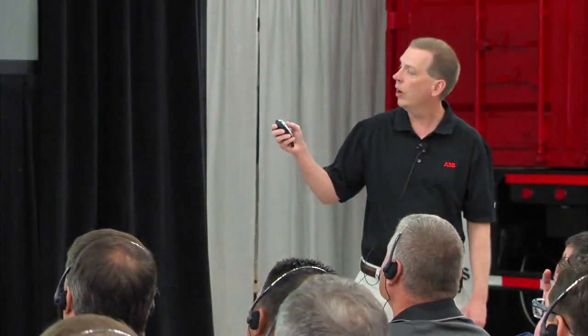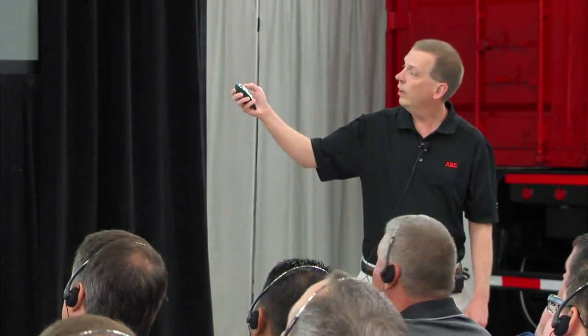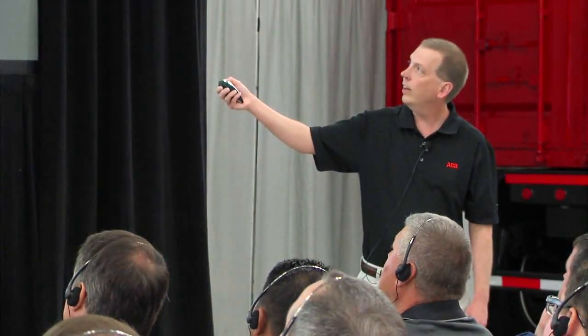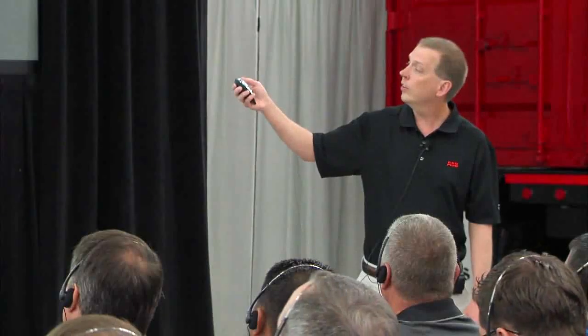What I was trying to say there is that if you could run half speed, then you can really save a ton of energy. That ends up being an eighth, because a half cubed is an eighth. But you probably can't run at half speed. That's not realistic. But there is considerable energy to be saved simply by slowing it down any amount you can.